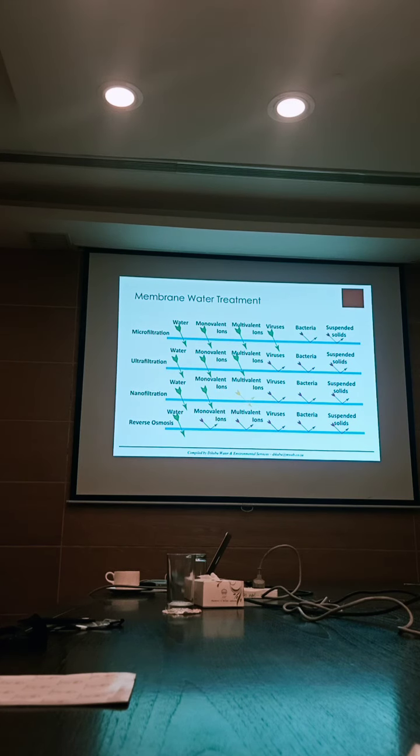I want to rather just, so there's a good illustration as to the different membranes and what it allows through. And it's a function of how much pressure you put on the membrane, right? The more pressure, the more gets squeezed through the membrane, the more your removal efficiency. So this slide is maybe a bit misleading here in terms of saying we get pure water coming out. In reverse osmosis membrane, water molecules only pass. Yes. Others are rejected.